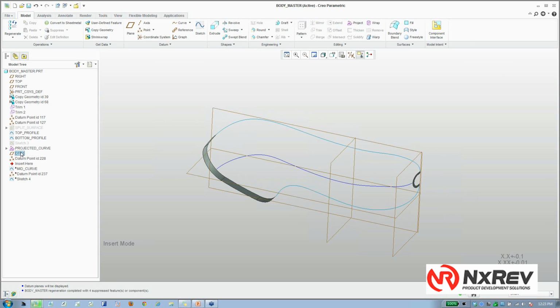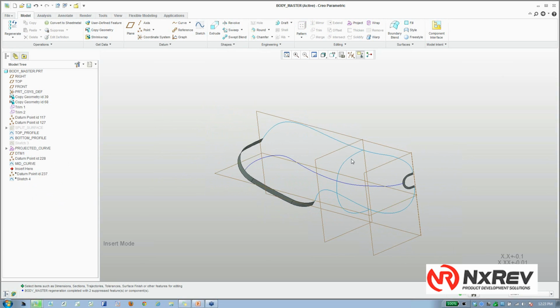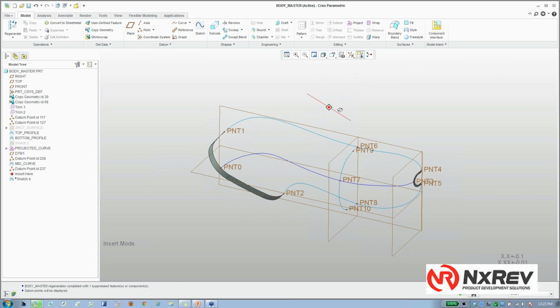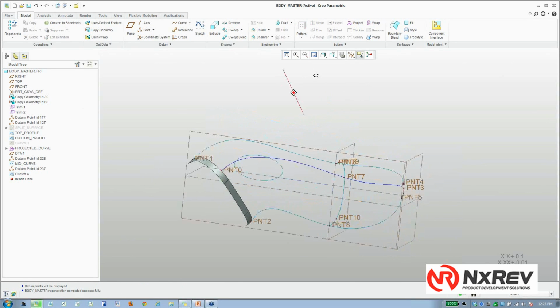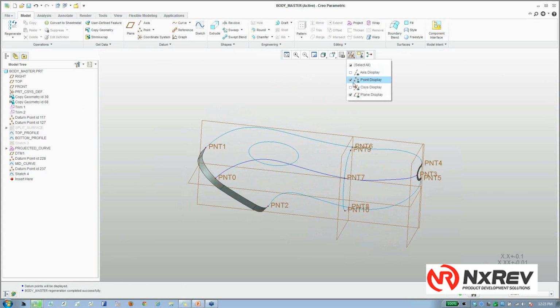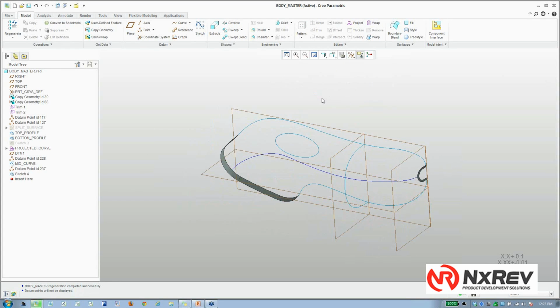So I'm going to offset a plane. You can see the plane is offset from this plane here by 45. And then we'll add that mid curve there, where we place the curve on this plane, and we just connect the dots there as well. So add some more points. The points are going to be used to streamline the surface a little bit. You'll see exactly what I'm talking about there a little bit later, and then we have some other features that we're going to be adding to that. So basically that's it. There's your framework.